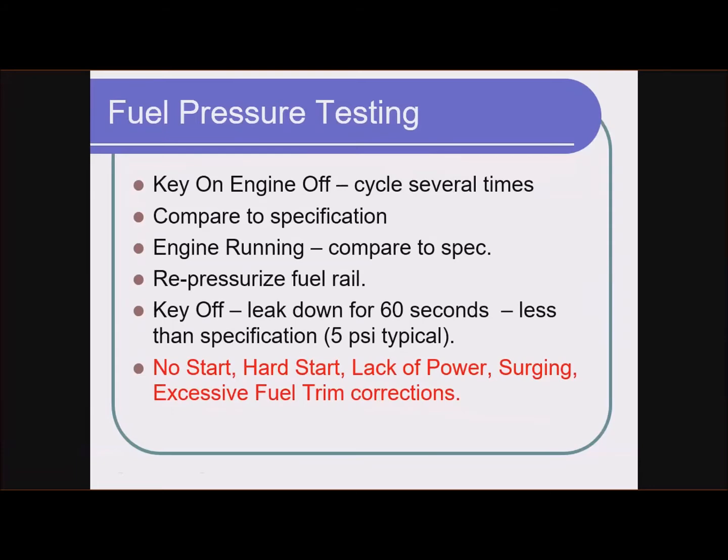Surging. So let's talk about what surging actually is, and that's when the power you're getting out of the engine comes and goes. So you get a surge of power, and then a lack of power, and then power again, and then no power. A lot of times this is referred to as a lean surge, because that typically happens when your air-fuel mixture is excessively lean. Could fuel pressure problems cause your air-fuel mixture to be excessively lean? Of course they could, if your fuel pressure is too low.